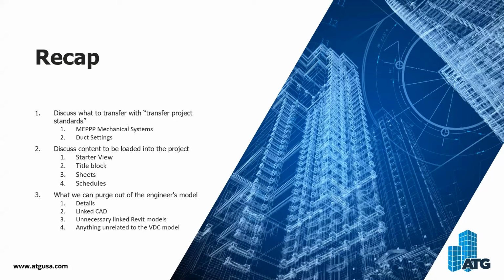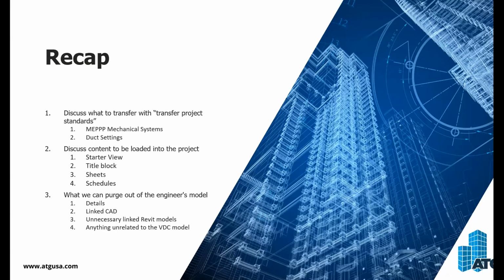And then you can wipe out any view templates, any work sets that they might have that you don't need, any filters that they might have that you don't need. You'll know what's what because of a distinct naming convention that we have with all our stuff. So you'll be able to differentiate as you purge some of that stuff out.